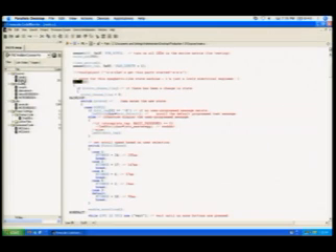Most embedded applications will have an infinite while loop and a driver stack, and it'll go round robin through each driver and determine what messages it needs to send based on all the global data it has. Now, in the application world, you hear that global data is bad. On an embedded device like this, there's no dynamic memory allocation. Everything is going to be determined at startup, and anything that dynamically allocates memory could crash your device, especially if you're doing safety critical applications. You don't want any of that. So everything has to be completely mapped out, well before you even write a line of code, for what your memory requirements are going to be.